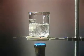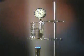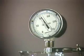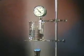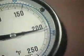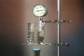Normally, whenever a phase change occurs, heat transfer takes place. We'll use this beaker of water to demonstrate a phase change and to identify a couple of types of heat transfer. As the water is heated, heat is transferred to the water, and its temperature increases. The heat that is transferred when there is a temperature change is called sensible heat. In other words, sensible heat transfer is heat transfer that can be sensed by thermometers and other instruments as a change in temperature.